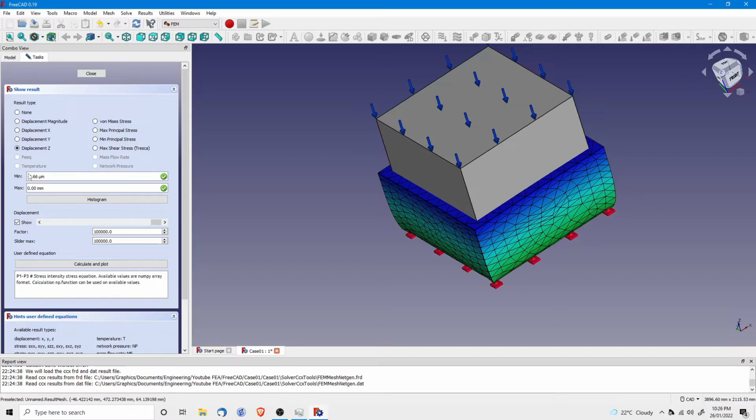So again, I'll rephrase. The displacement magnitude in all X, Y, and Z direction is 4.77 micrometers. Displacement in Z direction is 4.66 micrometers, and the maximum von Mises stresses are roughly 2 megapascal or 1.914 megapascals, and the minimum stress is 495 kilopascals or 0.495 megapascals.